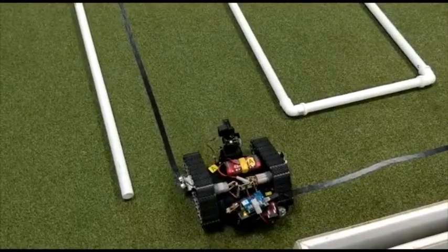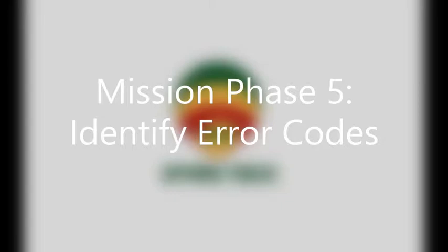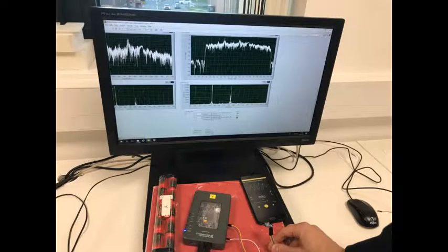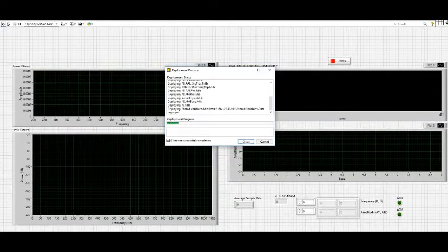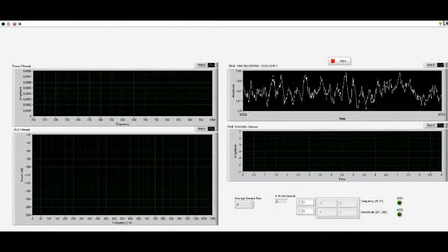This is our current audio detection solution. We're using an external microphone module connected through an analog pin to a battery-powered MyRio. The MyRio is using an internal 1 MHz hardware clock to create a sampling rate of 3 kHz.